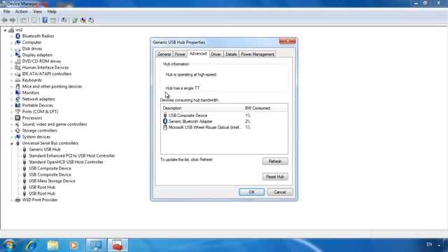The disadvantage of this is that all the devices must share the single TT, which can cause the performance of the hub to drop. This is only a problem if you have more than one USB 1 device plugged into this hub. A better quality hub has more TTs, and thus the workload converting from USB 1 to USB 2 is shared between them. Down at the bottom, you can again see how many devices are plugged into the USB hub. This time, however, you get an indication of how much bandwidth each USB device is using.